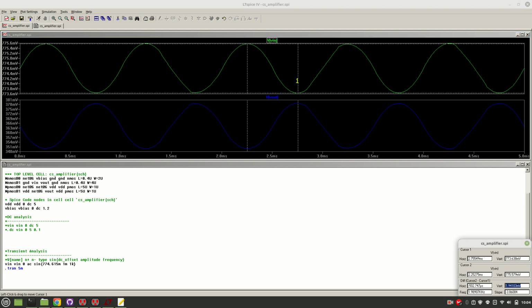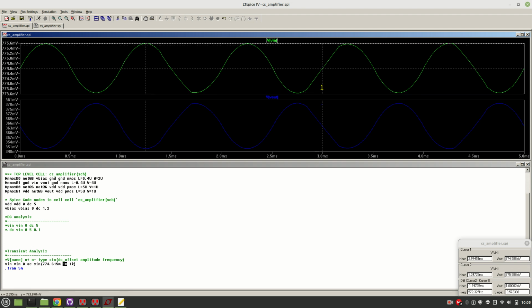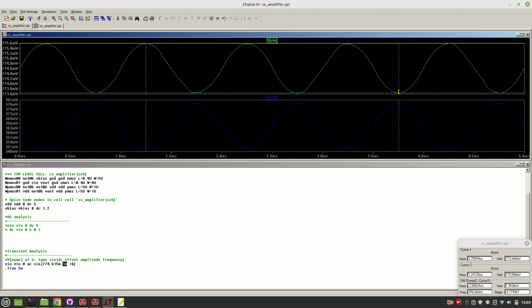That means it has to be 2 volt, because here we have 1 millivolt, right? 1 millivolt is the peak voltage we are giving. So here, from this peak to this peak, it is actually 2 millivolt. It has to be 2 millivolt. This is V in, right? So we see it here, 1.95, and it has to be 2 millivolt, but 1.94 something is there.